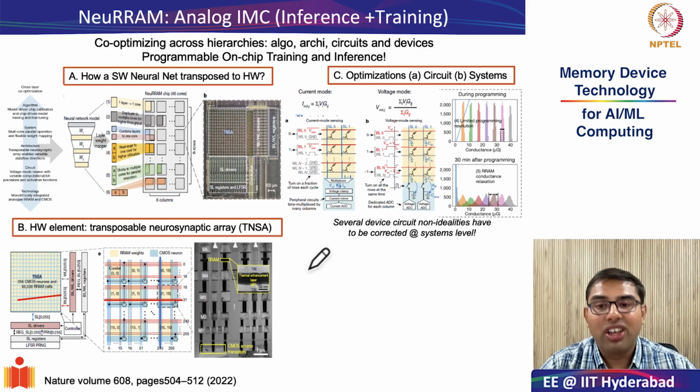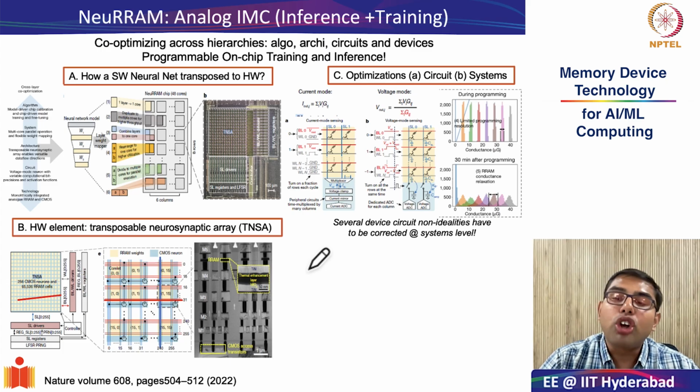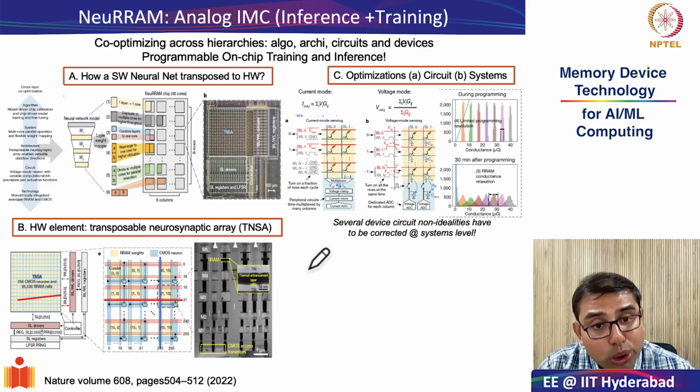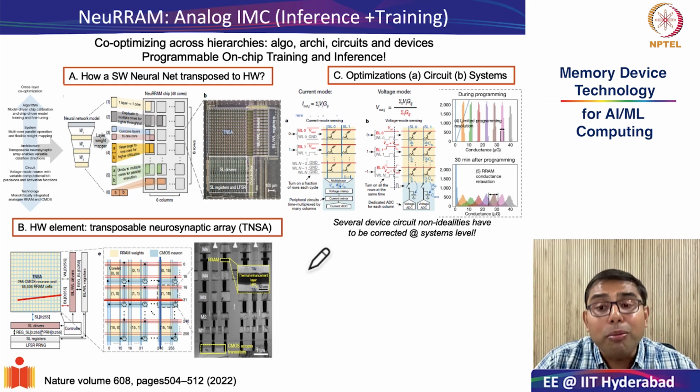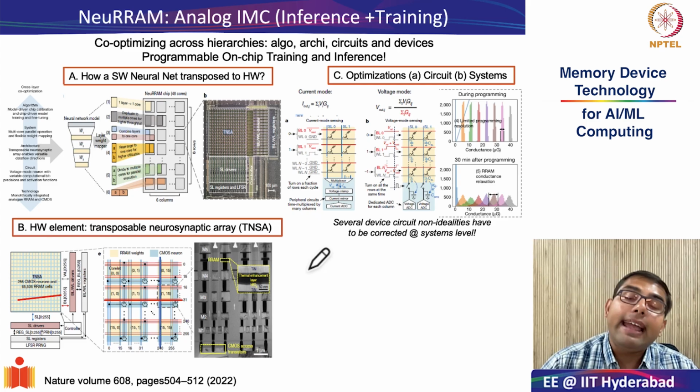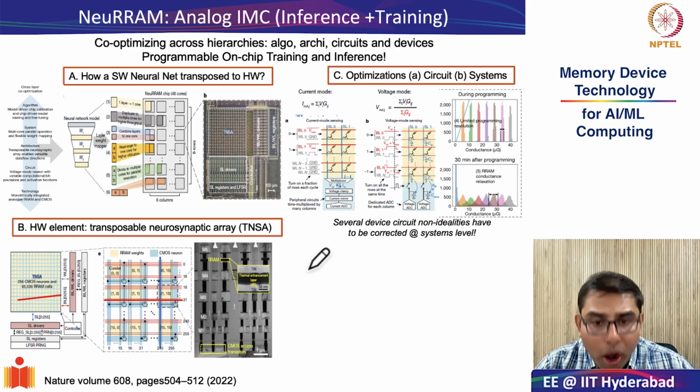To mitigate the non-idealities like non-linearity and cycle-to-cycle variability that come as part of your RRAM devices. Some of these challenges are essentially handled through program and verify schemes, while others are absorbed into system-level scheduling and data flow. All of these innovations improve the accuracy, but there is a cost of increased peripheral complexity.